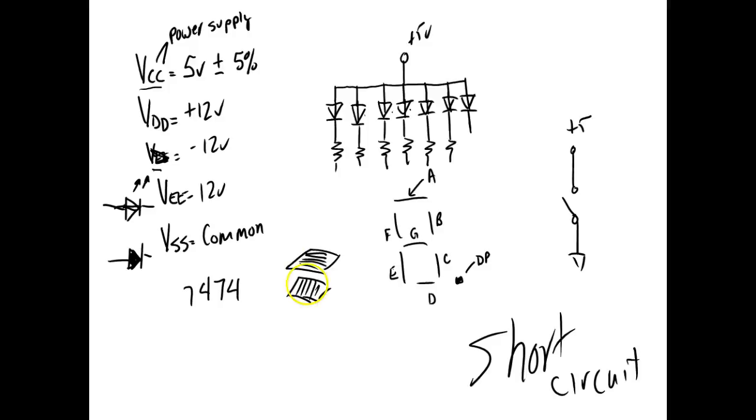And what happens when you put AC on the liquid crystal is they line themselves up. So if you shoot light in here, the light comes through and it's blocked by the other lens, right? Because they're polarized. When we put AC on it, it causes, and you can't draw it, the liquid crystal to form in a helix. It forms in a curve. And then when the light moves through, it follows the helix and comes out and it's viewed on the other side. So that's what you're looking at.